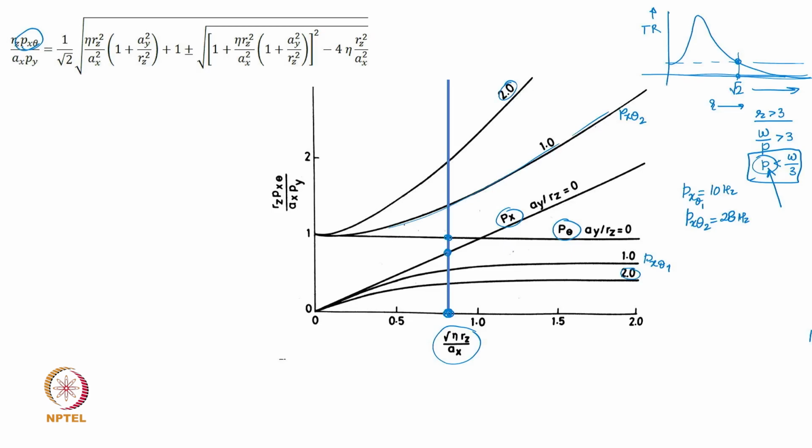So when you are designing, see, designing means what? You will fiddle with the value of the stiffness of the mount, so that your natural frequency is less than 1/3 of the excitation frequency. The condenser unit is, suppose, operating at, let's say, 46 hertz. Hypothetical case, it's not going to rotate at that higher speed, but just assume that it is 46 hertz, right? Now, what is your p expected? 46 by 3. Oh, I chose a wrong number. What will that be? Roughly 16, slightly less than 16, right?